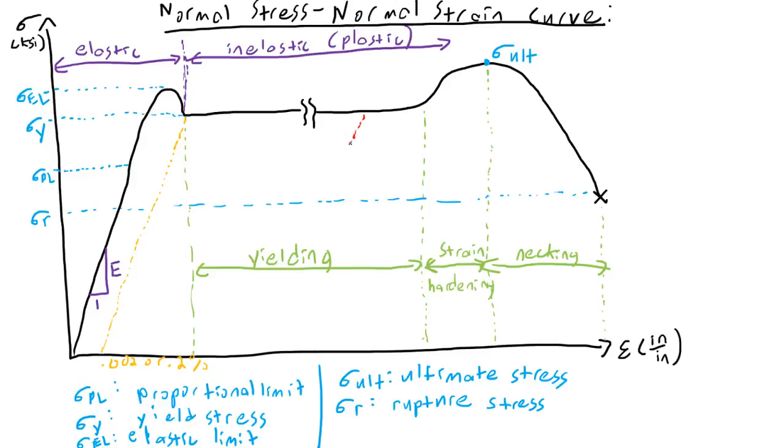It will actually follow an elastic behavior and end up about here. So if you release the stress here, it will follow its elastic modulus down and end up at a deformation here. This becomes essentially its new undeformed, unloaded shape. So when you're in the yielding zone, you have now resulted in permanent deformation.